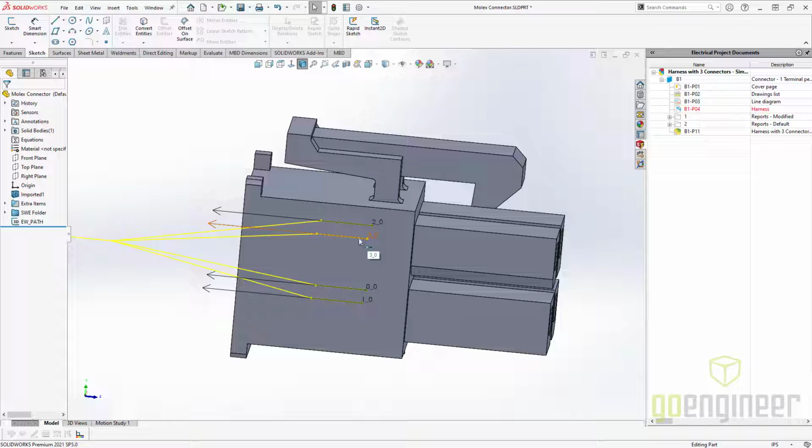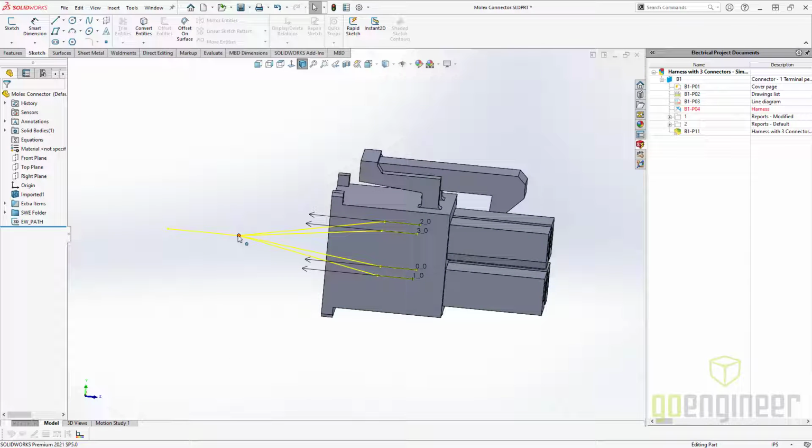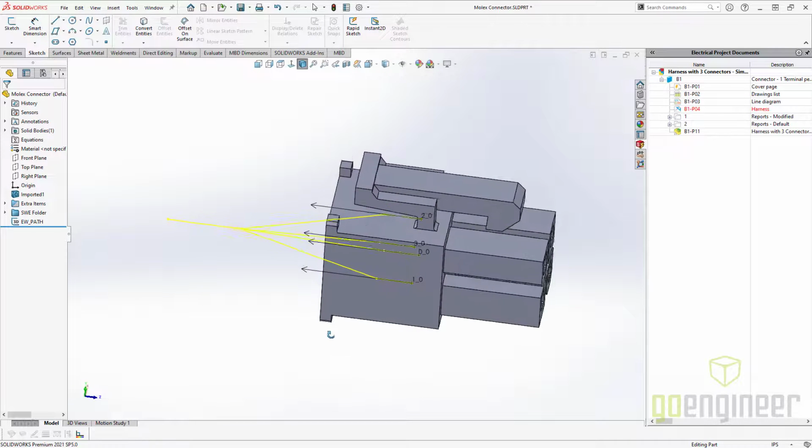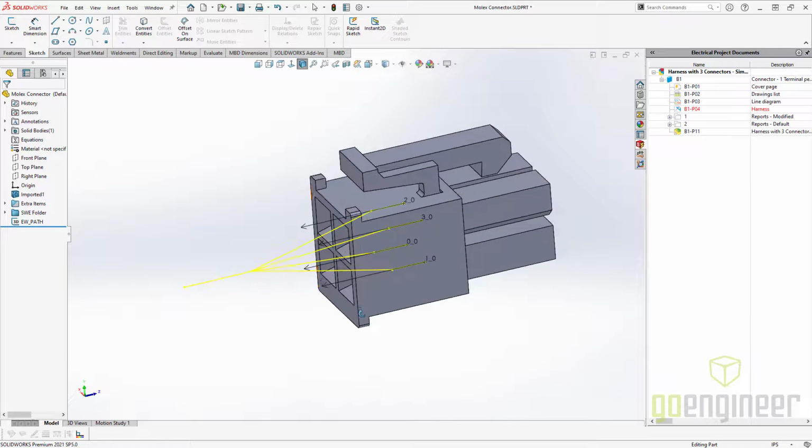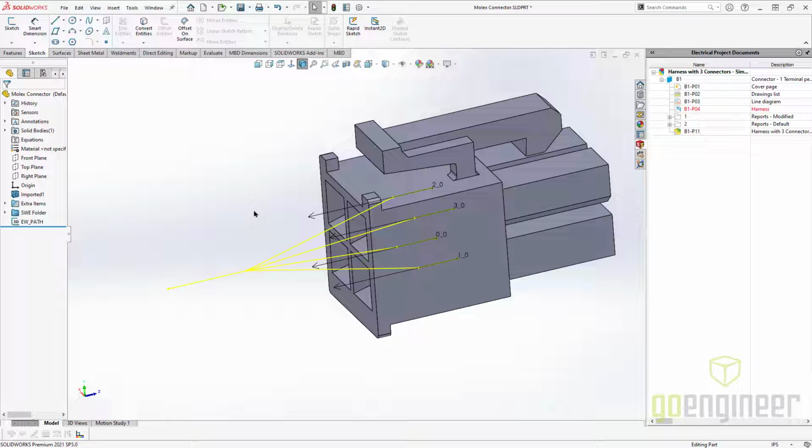These start out at a sketch point. They have a sketch relation along Z. I set it to a specific distance. I do another one out here in space, again maybe aligned with the origin of the part. Set a distance, and then I just connect the dots to get all of them. Again, you can get fancier with that. These are just lines that I'm doing, and I'm sure with some of the other webinars in this series, you'll see other options there too. But you have the ability of deciding what you're doing with that.